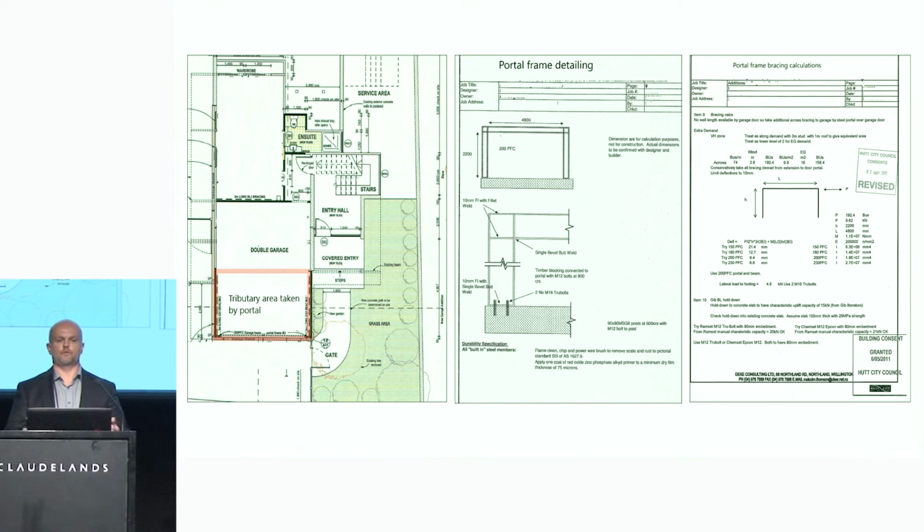So, you've got a flexible diaphragm, or you're assuming a rigid diaphragm, or whatever else it may be. Angela Liu's work says that in residential, then, you should be looking at a fairly rigid diaphragm. When I was a real engineer, then we used to assume that the diaphragms were reasonably flexible, but it turns out that that is incorrect.